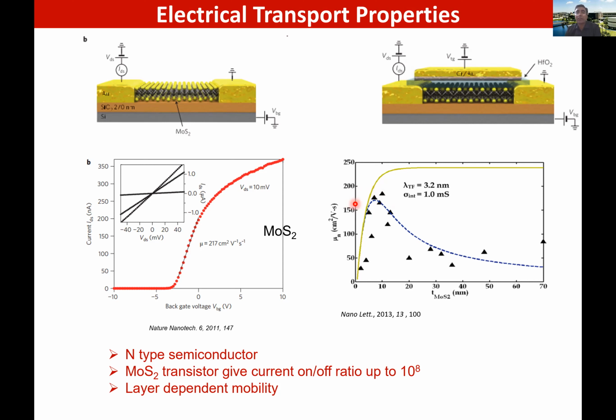If you have a dielectric that is really nice and high K, the mobility is expected to be great. If you have a substrate that is atomically smooth, your mobility will be extremely great. And if you have a contact that has no Schottky barrier, you will also have a very good mobility. So these numbers have to be taken with a grain of salt, because this device here is unoptimized, okay?